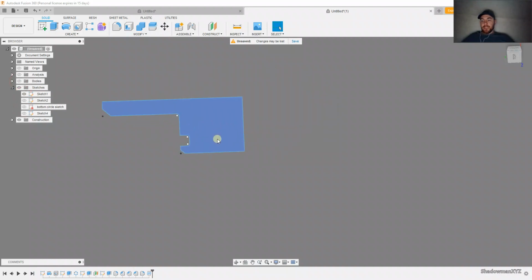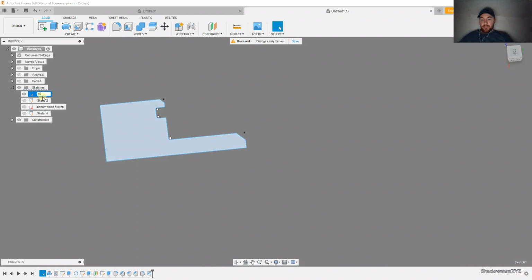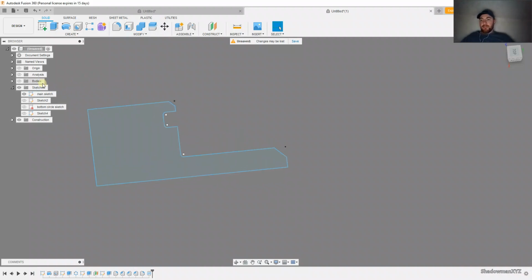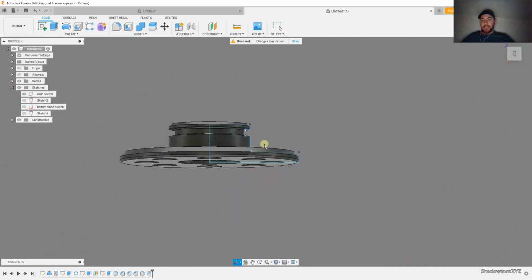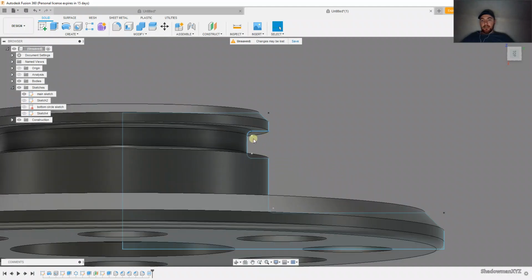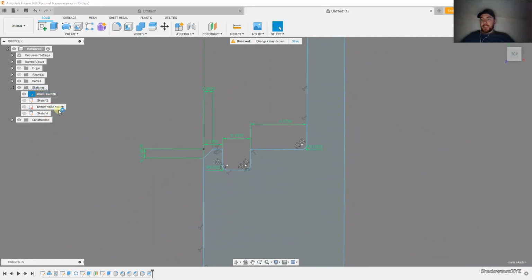This first one is the main sketch. It's the flat 2D sketch. I can just tell it that's what it is. So just click on it and say, main sketch. Enter, boom. So if later on in the design work something needs to change, like something with this groove, I can always go back to the main sketch, right click and edit the sketch.